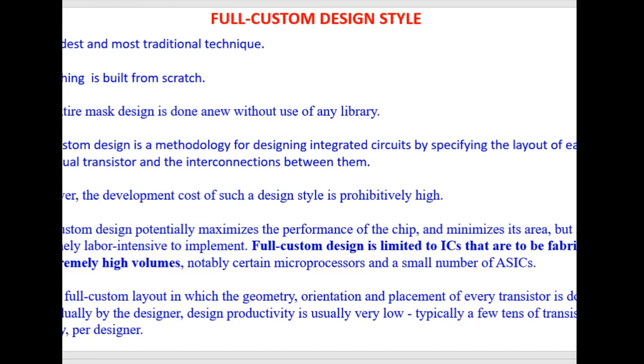So this was about full custom design style. Remember the points that this is one of the oldest techniques, and this requires everything to be built from scratch, and hence, since there is no availability of any library as such, the development cost comes out to be very high for this particular design style, and hence this is suited for those kinds of ICs which are required in millions of numbers.